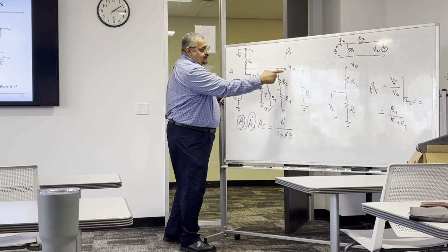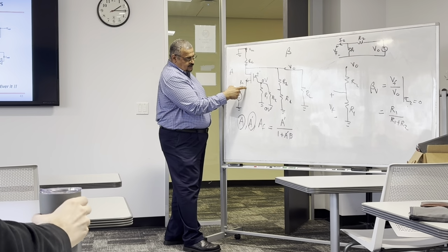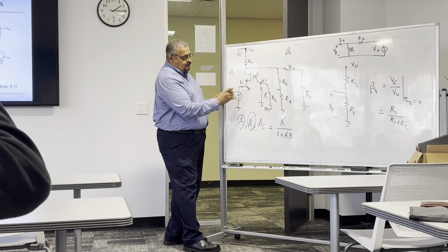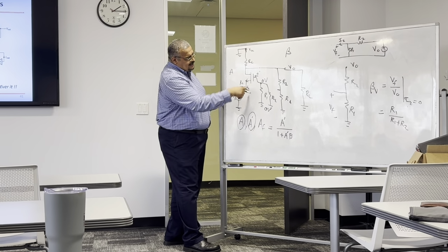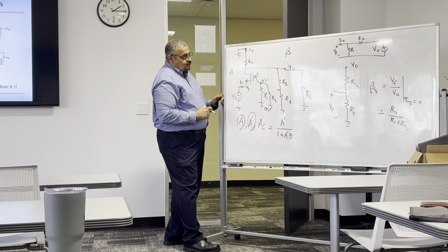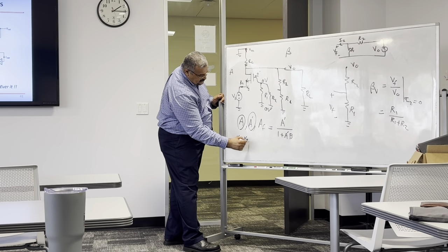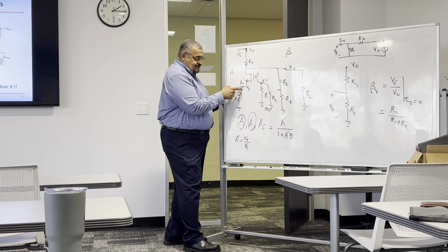Because what's V out? What's the gain? It's going to be V out over VS, not this voltage, not VGS. Or actually VG, okay? Because S is not ground. I assume here is not ground. So the gain A prime now is V out over VS. And this includes this and this.